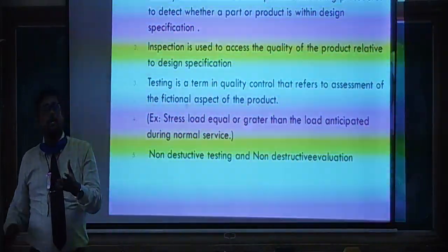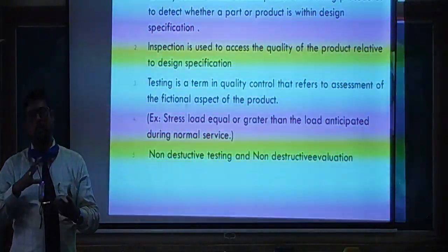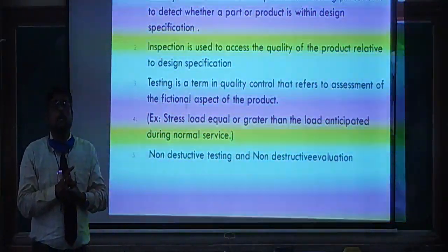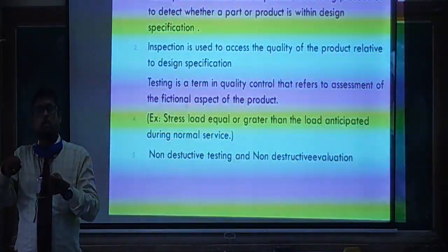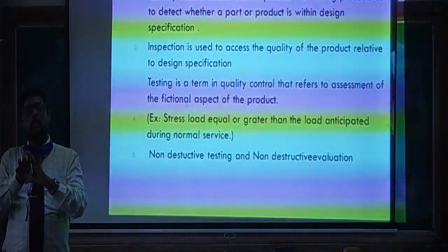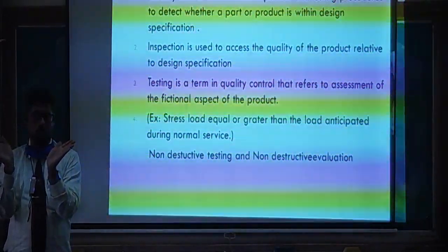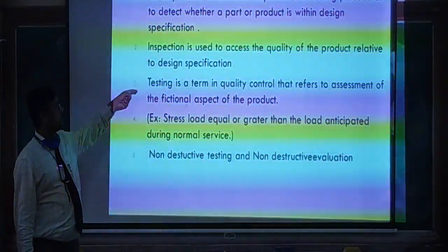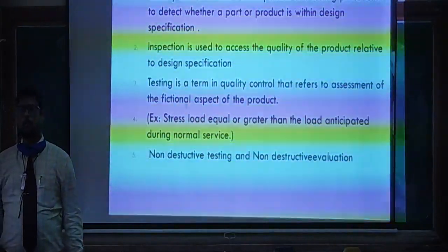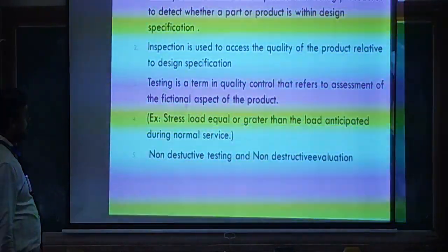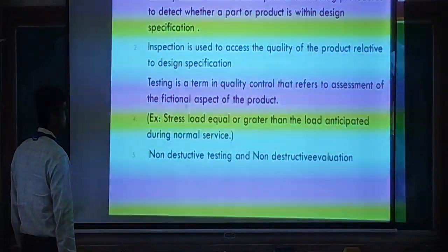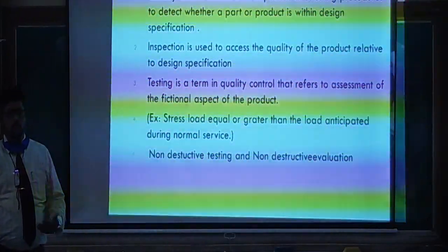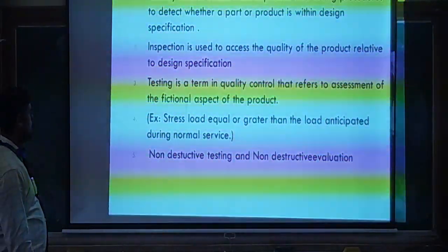The functionality is that the water is flowing with high pressure, or the oil is flowing through that particular pump with the help of high pressure. When you close that particular valve, at that time that pressure will be induced on the valve, so it should sustain that pressure. That is what we are doing in the testing, with the help of some test rigs. We are checking the failure of that particular part, or for how many cycles it will fail. So that decision we will take with the help of testing.